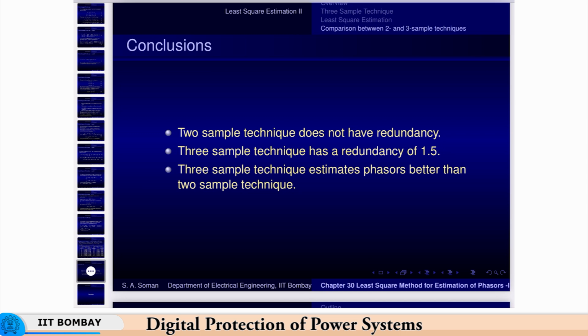Okay. So, the answer to that is, people have gone for 12 samples, 16 samples, 20 samples is by far the number of samples used for the commercially available relays. 12 samples will actually give you the advantage that you have 2 pi by 12 theta. So, that is pi by 6, so you have multiples of 30. So, your computation becomes easier.